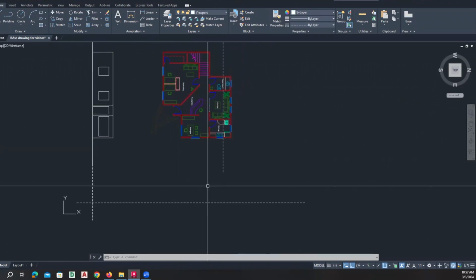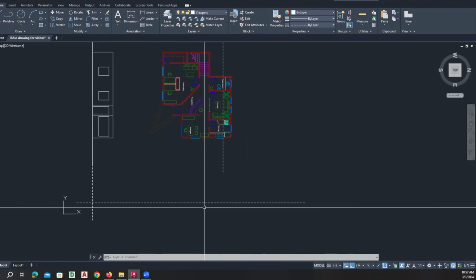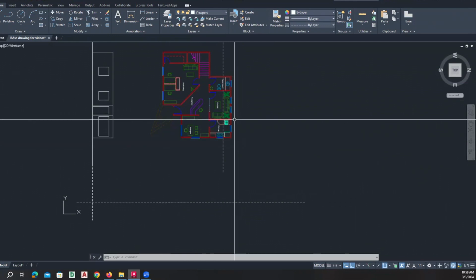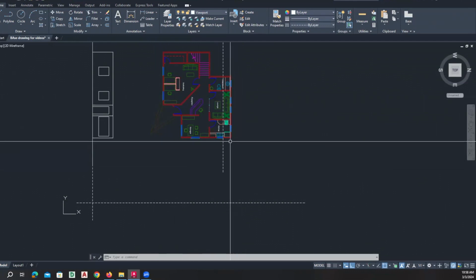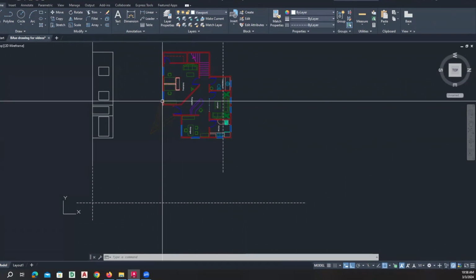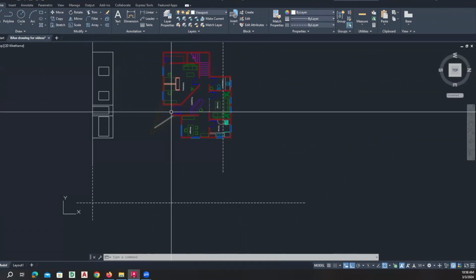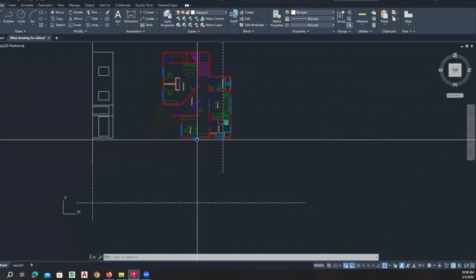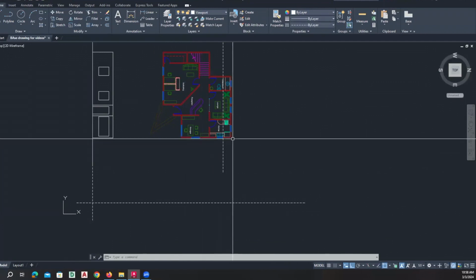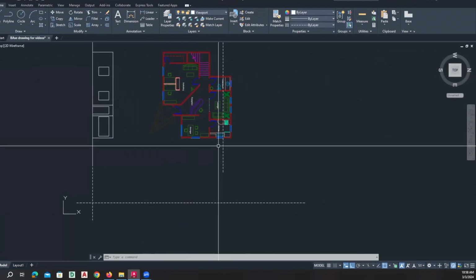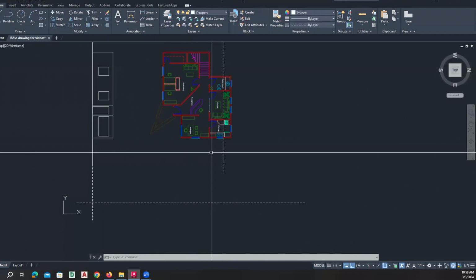So now I'm going to set up this drawing so that I'm drawing my elevation parallel to the side of the plan. And again, because we're projecting it, anything we drew in plan already, all we need to do is project it. We don't need to recall the dimensions of these windows. We don't have to look it up on our survey. It is already drawn in the plan, assuming you drew the plan accurately to begin with.